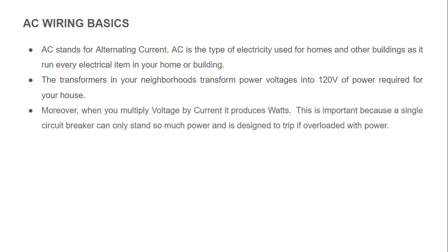So when you multiply this voltage by current, it produces the watt, which is basically the power one device uses. This is important because a simple circuit breaker can only stand so much power and is designed to trip if overloaded with power. We all know that we have so many safety devices like the circuit breaker, fuses, and a few more, which are specifically designed to break the circuit once we have an overloaded supply of voltage